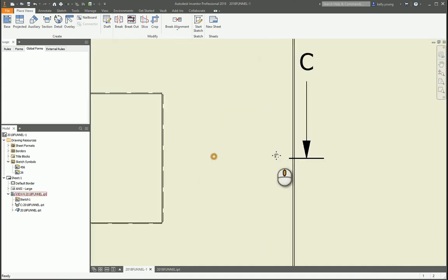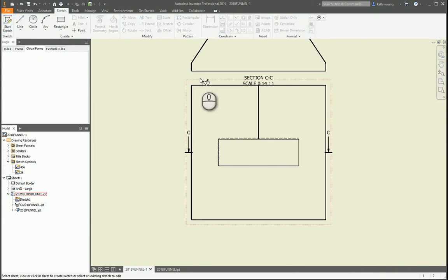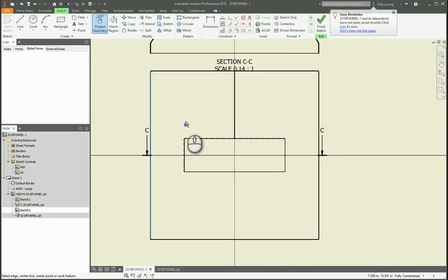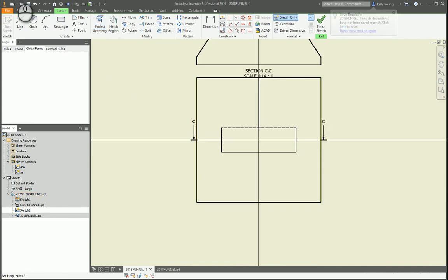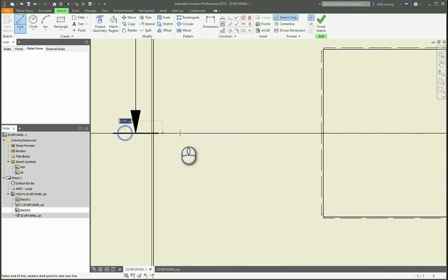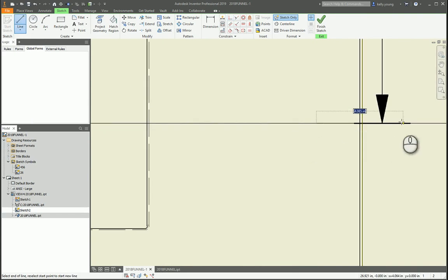but you also want that little dash in here. So what we're going to do is create another sketch. Just hit S, or you can go up here to the sketch tab, start a sketch, select the actual view. Now you're in the view. You can go ahead in here, turn our sketch again, project our geometry, and then draw a line. So if we basically draw a line from there to there and have it stick on that point, and then again to here.